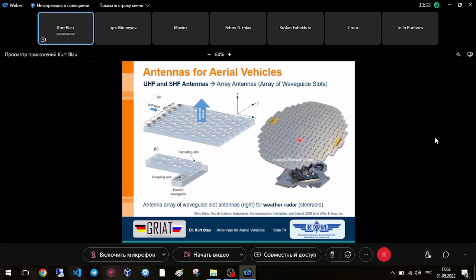And so you can achieve with this antenna a certain diagram. But again, this is a new type of antenna, because we have here not a Yagi antenna to concentrate the radiation in a certain direction. In this case, we have a so-called array. It means we have elements localized in the same plane, and all elements look in the same direction, meaning in our main radiation direction.